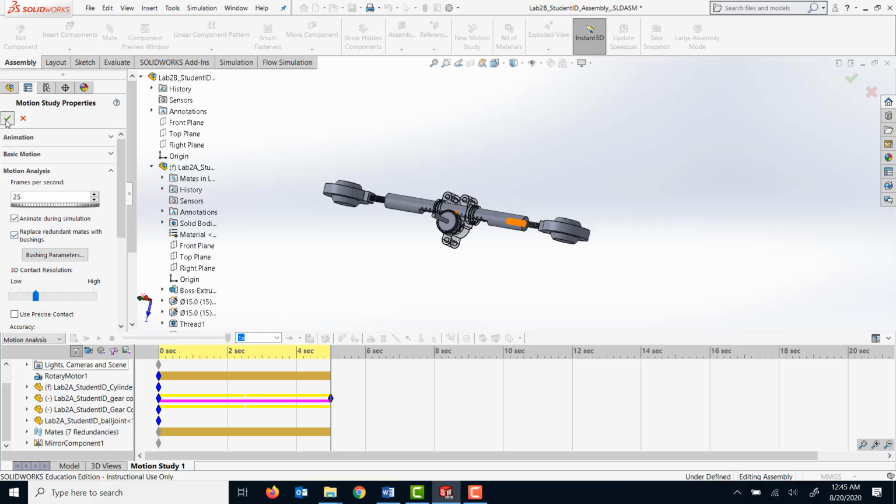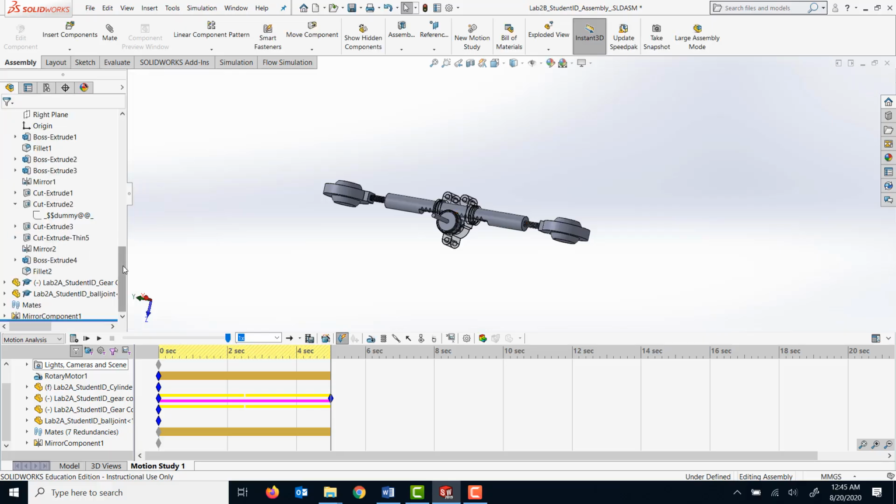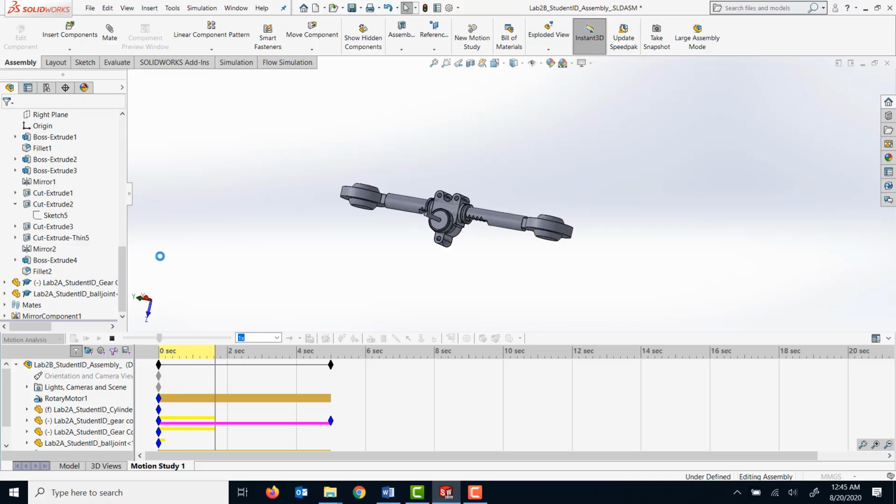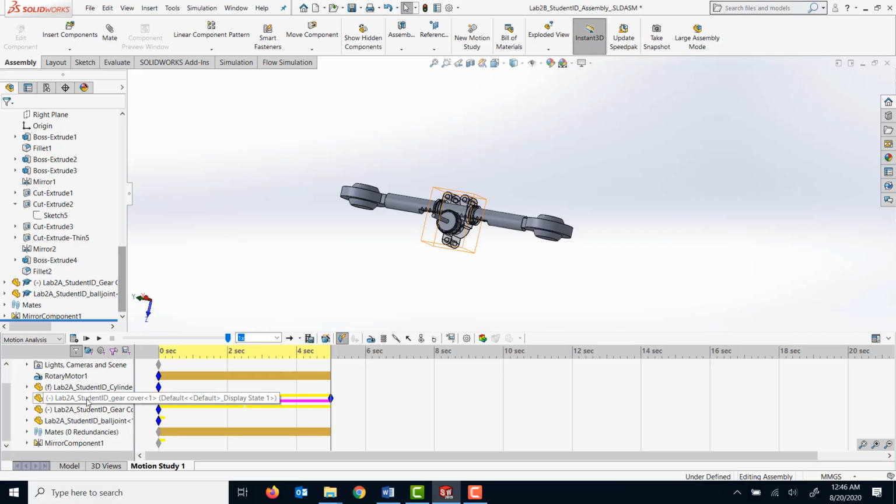It doesn't work all the time, so I'm going to see if it works here or not. Otherwise, you have to go and clean up your assembly manually. If you don't remove the redundancy, sometimes it can create incorrect results. So I'm going to solve it again. In here, if I review, now there's no more redundancy.